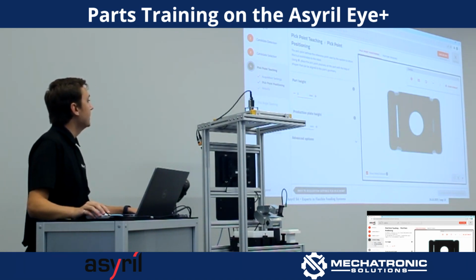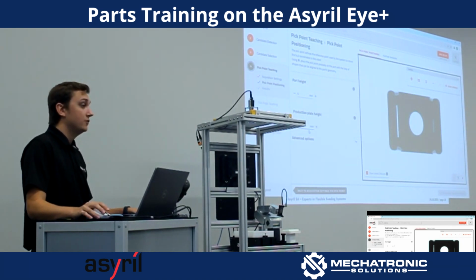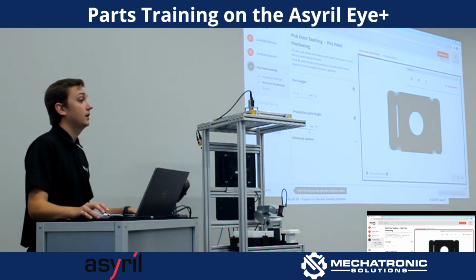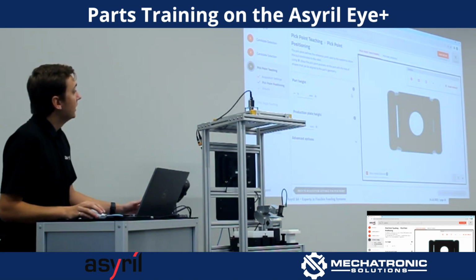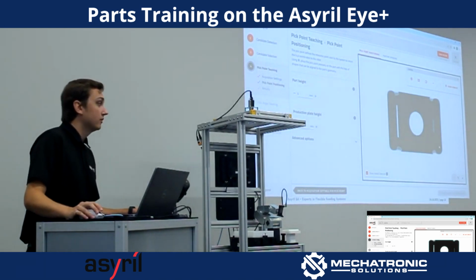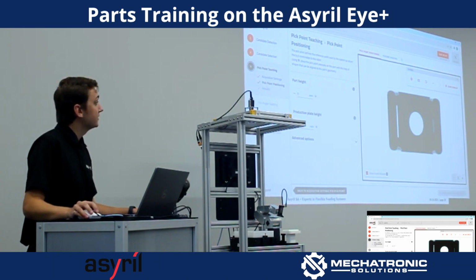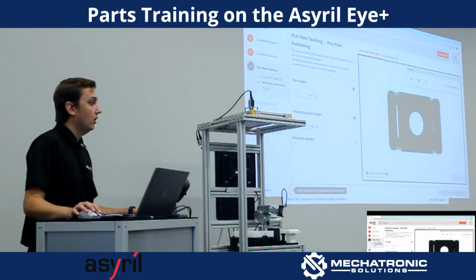And then the production plate height is filled in depending on your cube size. So 13 millimeters is standard for 240. If you create your own production plate and it's higher off of the platform, you can adjust this as you see fit. Moving in, I+ is going to create this outline around the part here. And it's going to try and match this outline to every part that gets to this step, and match a pick point to it. And so we want to mask features that are either not on the plane of picking or are unimportant to us.